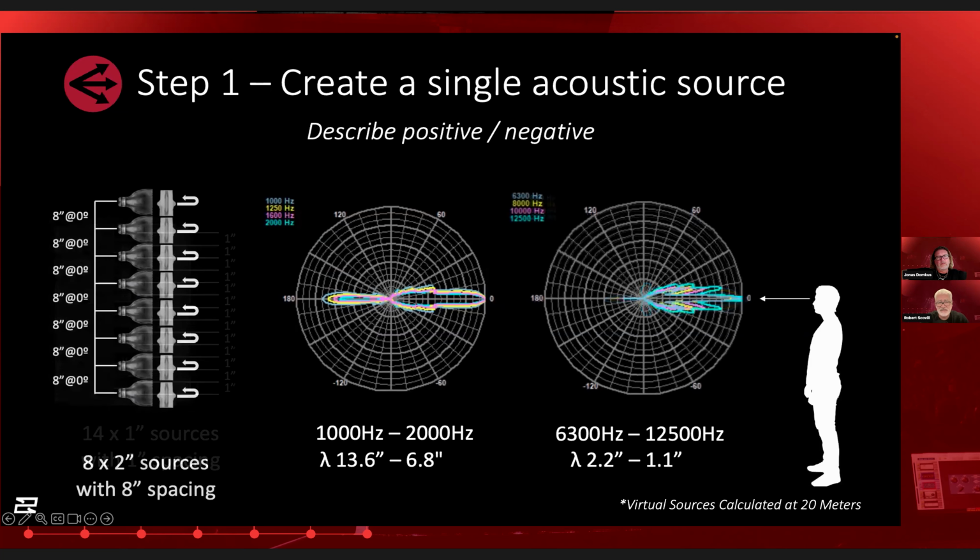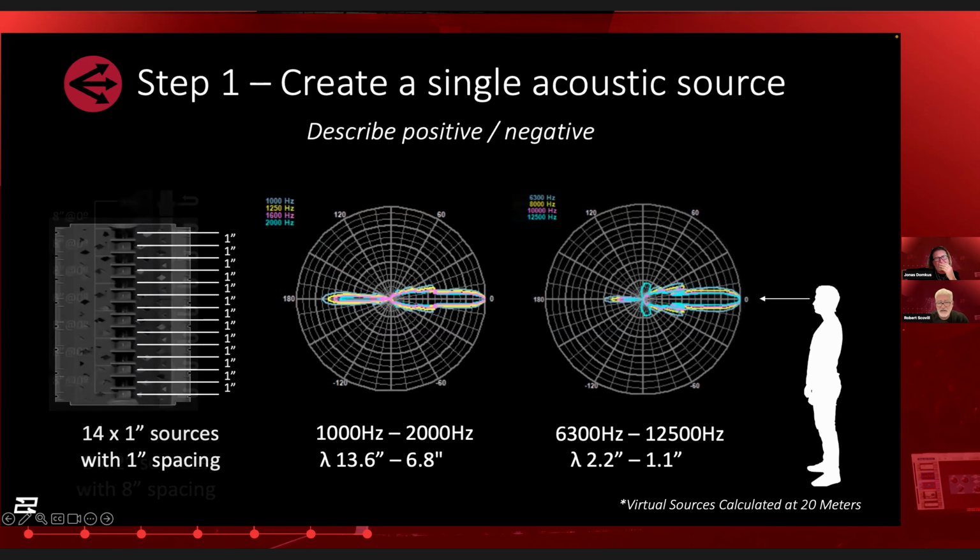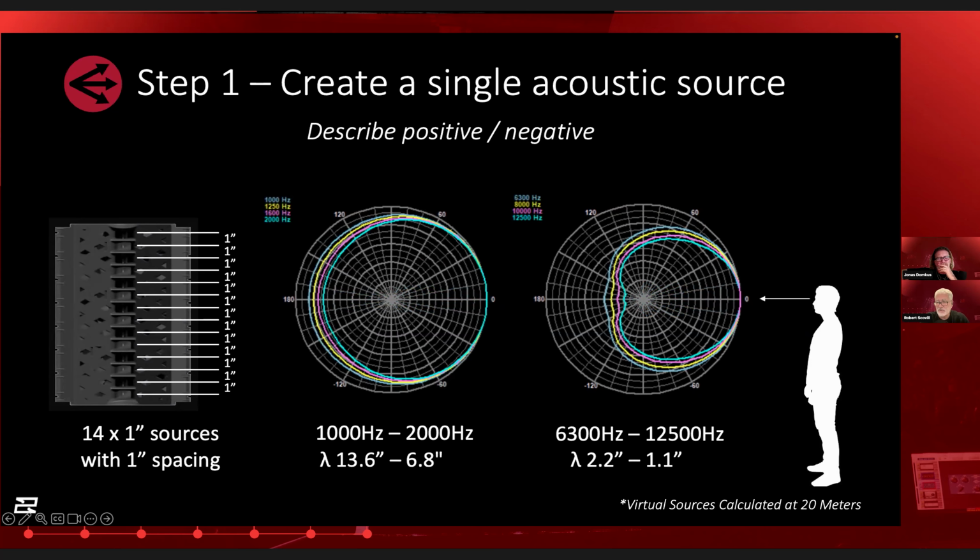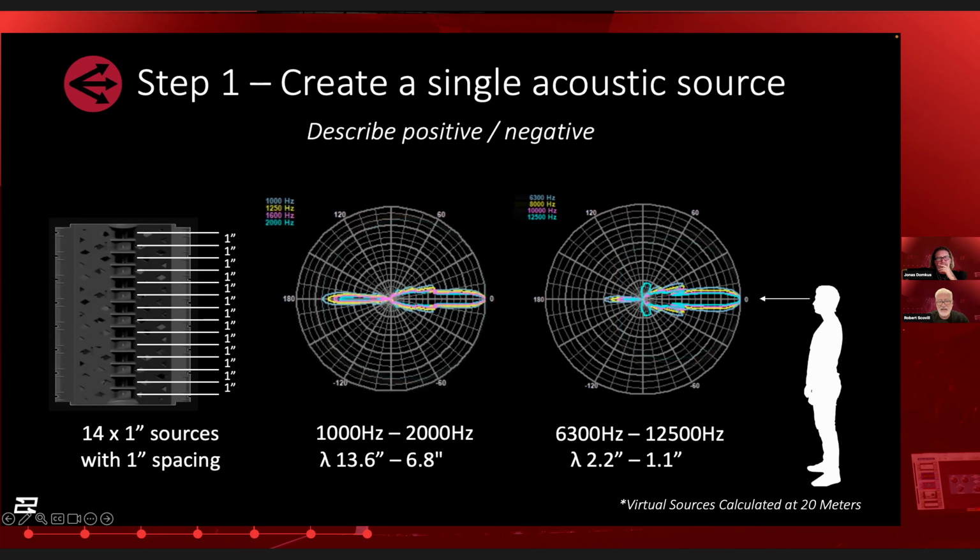Remember, in this situation, we've stolen the ability to overlap, right? This is all just being measured out at distance of the full array. So we see the full collapse of it. Here we're doing the same thing, but given that we have the overlap and we have DSP available for every driver within this horn segment or array segment as it would be, we can actually create any size polar, any shaped polar is what I should say there. Anything between that and that.